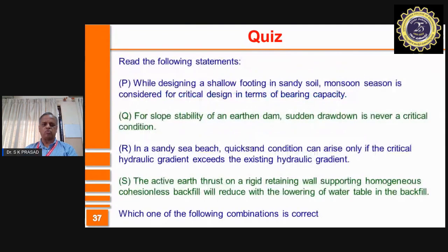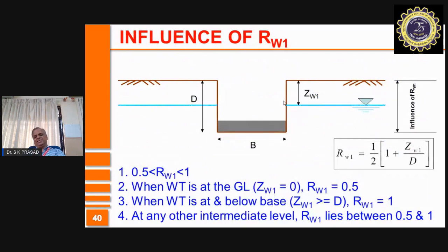Now, let's go back to the question here. While designing a shallow footing in sandy soil, monsoon season is considered for critical design. Naturally, during monsoon season, groundwater table is likely to rise up. And in the worst situation, it will rise up to the ground surface. Otherwise, also, it is considered as the critical design in terms of bearing capacity. Therefore, the answer to this is yes.